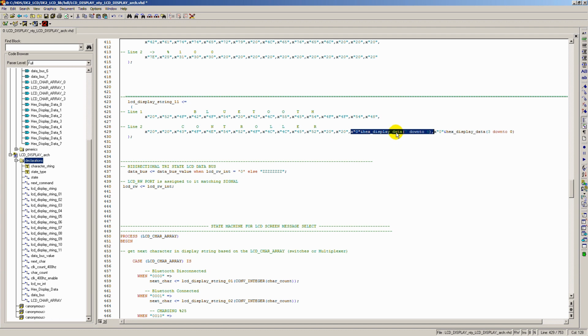So you can go in and create several of these if you wanted, and then map them out to different hexadecimal variables within your string values, and have those mapped to a series of input switches and have them display custom characters. So just make note of that. This particular variable that I have laid out here, each of these is mapped to a specific series of input switches that we'll talk about now. So this one here is for 7 down to 0, and then the last one here is from 3 down to 0.